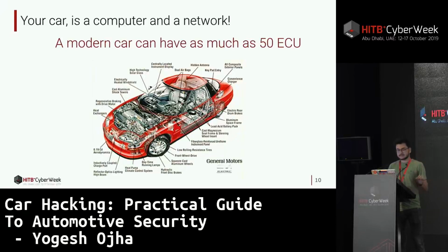Your tire pressure sensor being synchronized to the infotainment system, the internal combustion engine sharing data with the infotainment system, and all this sort of information has to be communicated. And for that, you need a network. As modern automobiles contain as many as 100 electronic control units, the safety of the vehicle relies on near real-time communication between the various units.